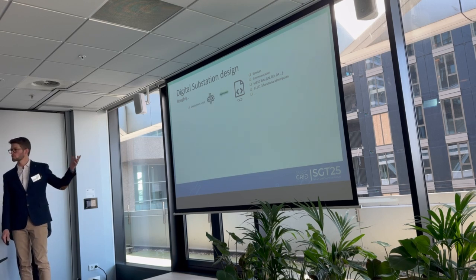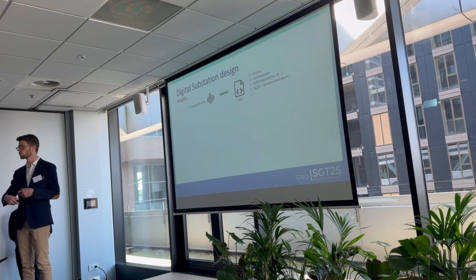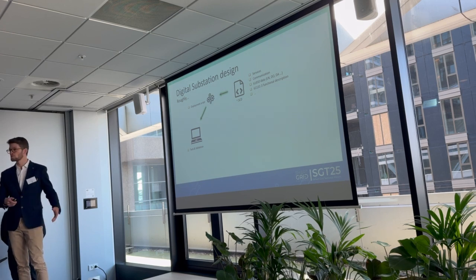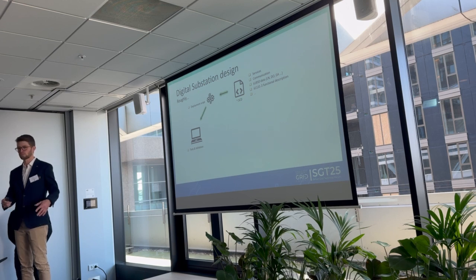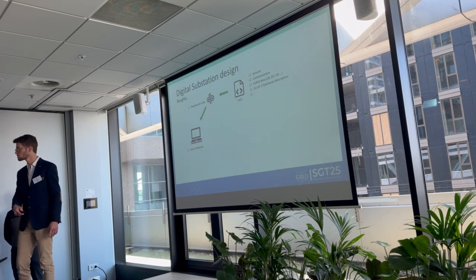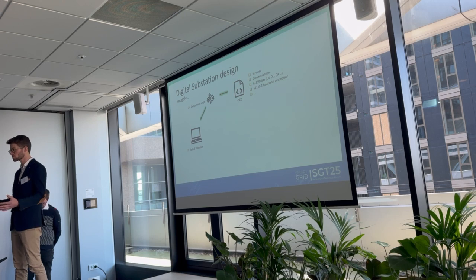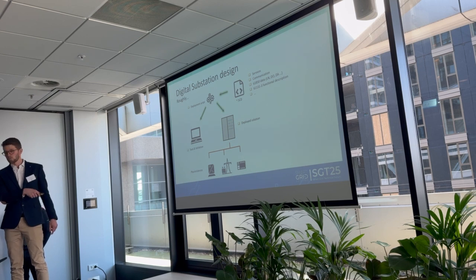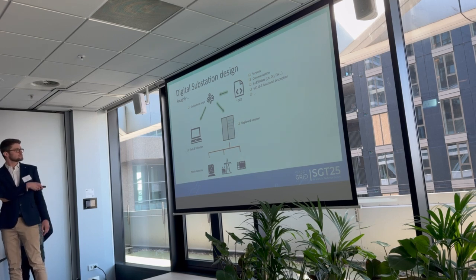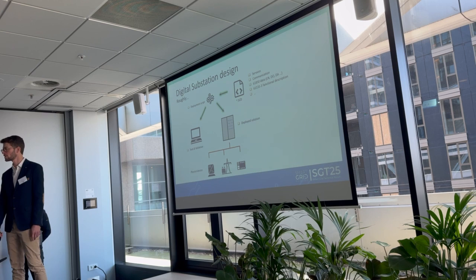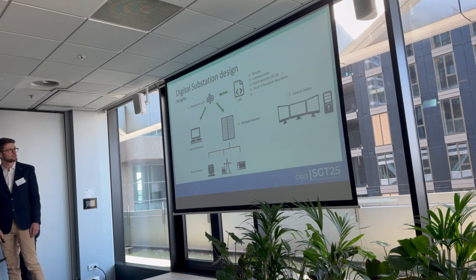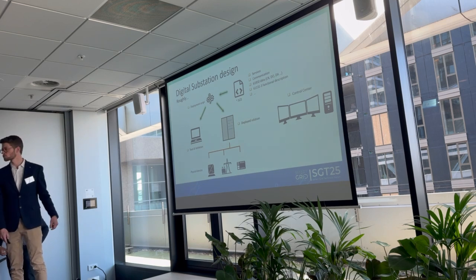So all of this, 850 communication, functional description in one file, you put it in a deployment script. So you build your automation, you build your communication, and then you can deploy it. You can deploy it, as said, as it's virtual and digitalized, on a Windows PC, for example, for the simulation. So of course it will have few other devices to test, but you can deploy it on a simple platform to do some tests already in-house. And then you can deploy it once it's validated in simulation on the real machine, and then communicating with real physical devices. And above that, you have a control center, you have your SCADA to control everything.